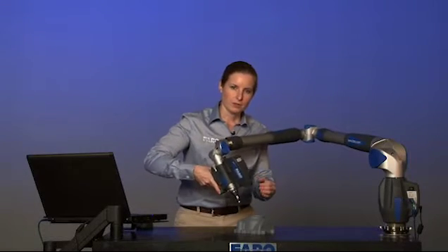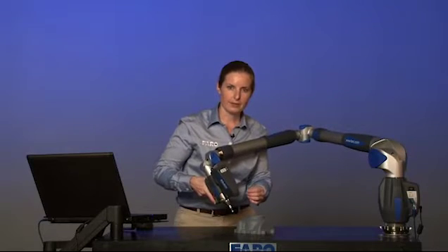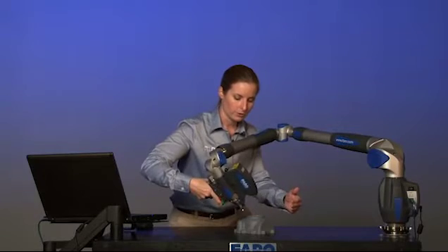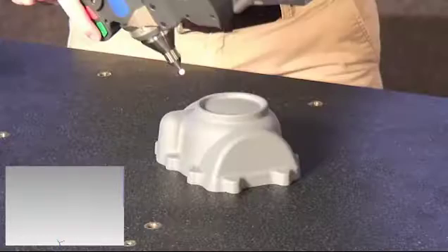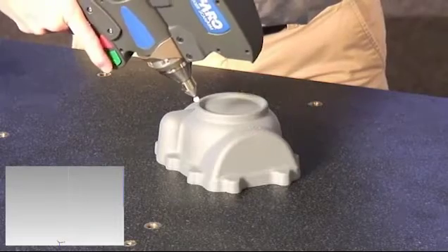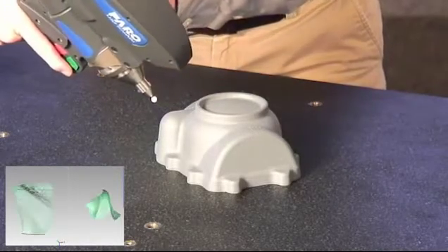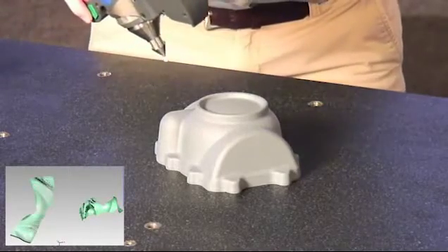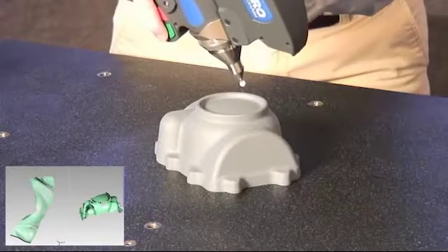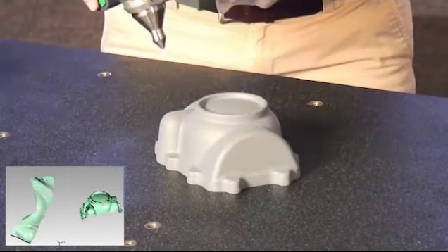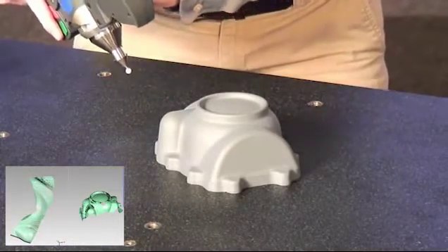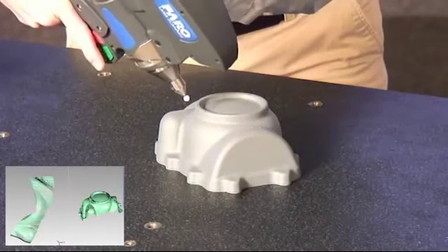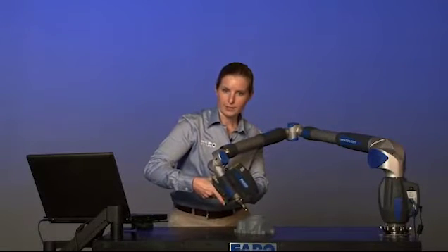You want to cross your part in a similar method as you would painting. So you see your red stripe on the part, and we're going to cover the part in a sweeping motion. Press the green button to activate the scan, sweep past the part, and repeat so that you cover the entire part. You can press the green button to pause at any time.